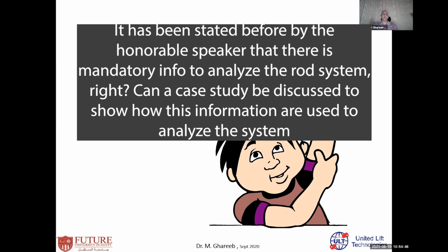But yes, I expected problems because the water cut increased or there is some CO2, H2S while I am using metallurgy that is not suitable downhole. What size of coupling? I am running in deviated wells, and I have a rod and tubing that maybe is not designed in a very good way. What type of sinker bar I used, and so on.